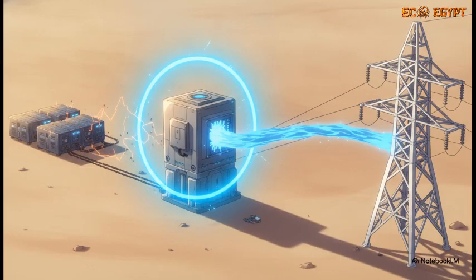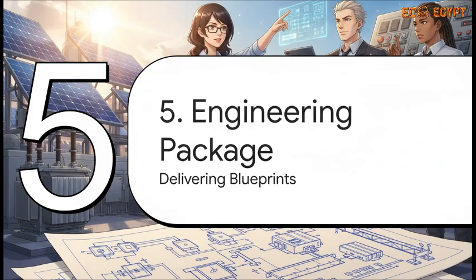And here is the real-world consequence of all those calculations. If the grid operator demands more reactive power support than your 30 inverters can safely provide while still pushing that active power, well, you've got a deficit. And you can't just ignore it. You have to actively design, size, and install physical, external compensation hardware. We're talking localized capacitor banks or dynamic STATCOM systems to bridge that gap. Doing this ensures your PV plant acts as a compliant, stable, and genuinely helpful generator for the grid, instead of a disruptive one.